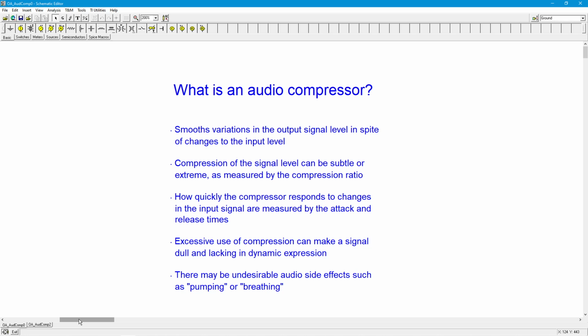Instead of the LDR, another way to approach this is through a JFET. You can use a JFET in the ohmic region, right? So it acts like a voltage-controlled resistor. And I have some videos of using FETs in the ohmic region, so you might want to take a look at those. It's basically the same idea as the LDR version. But I want to look at something different.